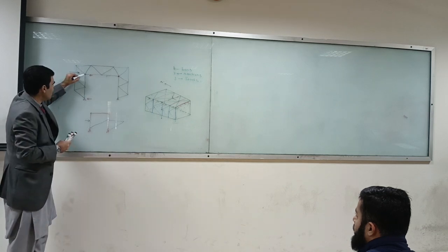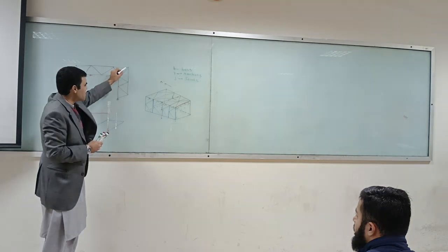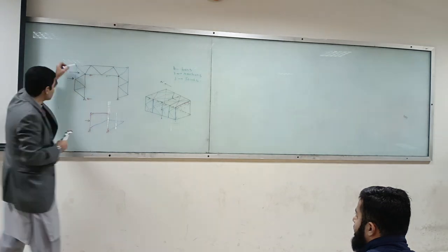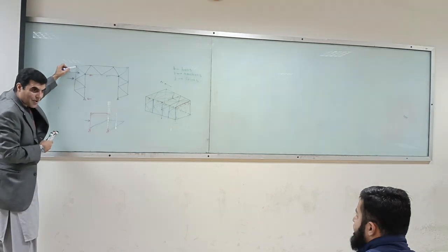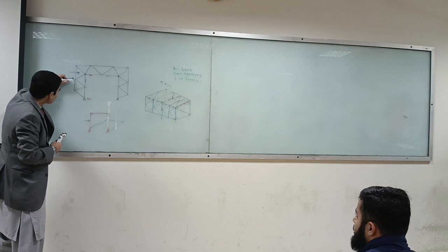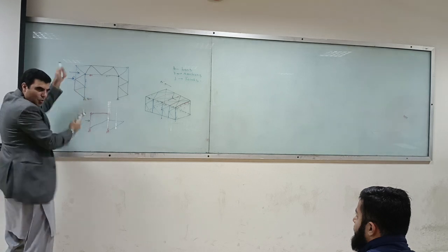This is also pinned, but now this is stable. Why? Because I fixed this. This is now fixed. A moment which can appear over here, that moment can be taken by these members. This one and this one can take that moment.